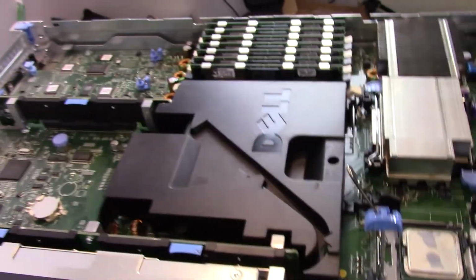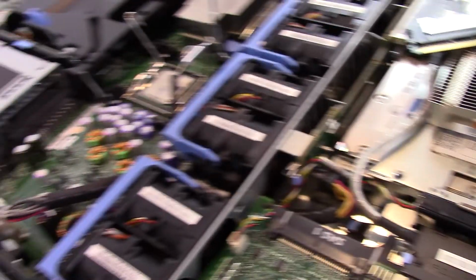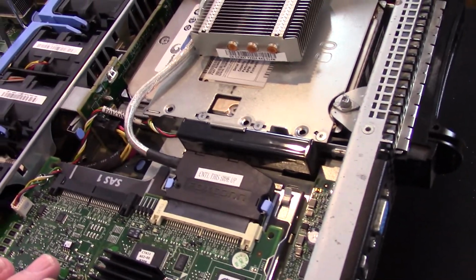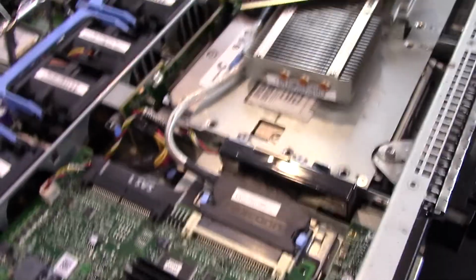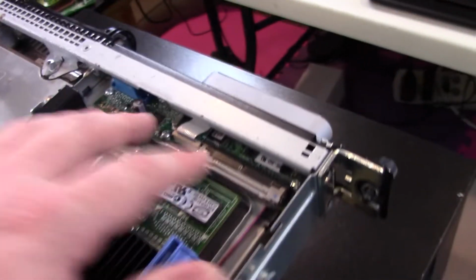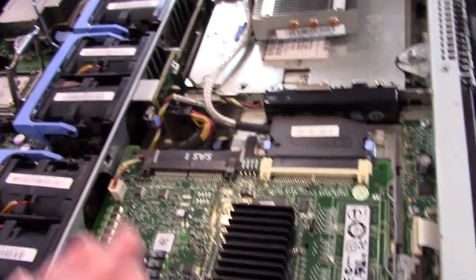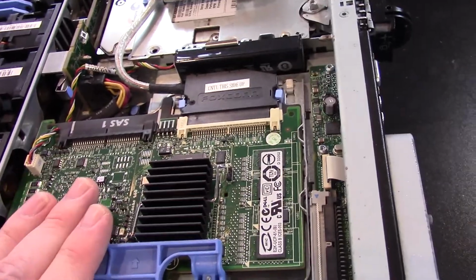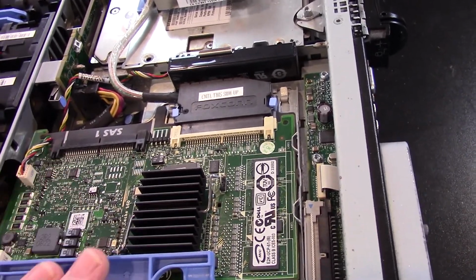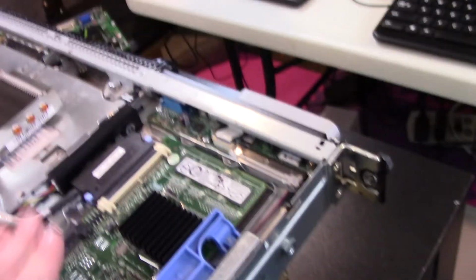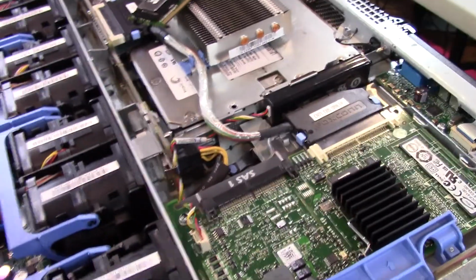One last thing I should mention is something you'll see here: the motherboard is quite a bit bigger. It's more laid out like this, and that's because it's far more modular. So over here, we have controllers just for hard drives, and they could be swapped out without replacing the whole motherboard. We also have daughter boards, which is what you call little boards that sort of aid the motherboard. And they provide some dedicated tasks. This one over here handles the hard drives. And breaking it up more means that you only have to replace the one daughter board instead of the whole thing if something goes wrong.